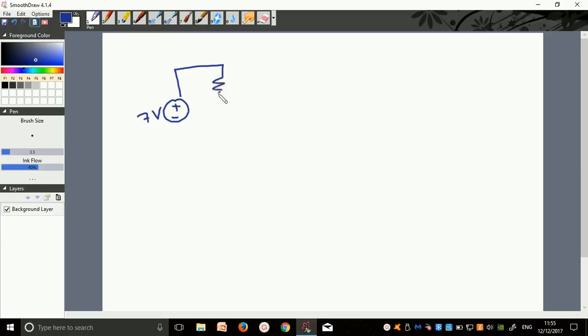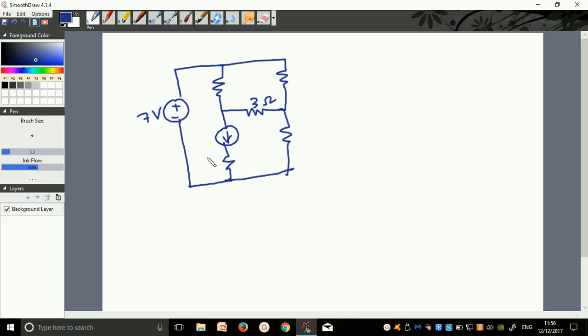Say I have got this one. So this is 2 ohms, 1 ohm, 3 ohm, and 2 ohms, and 1 ohm, 1 again. So I've got 1, 2, 3, 3 meshes. So this will be I1. In this mesh, suppose I2 is flowing, I3 is flowing in this mesh. So suppose I need to find the current through the 3 ohms resistance. So what is the current through the 3 ohms resistance? That is, I need to find I2 and I3 both.